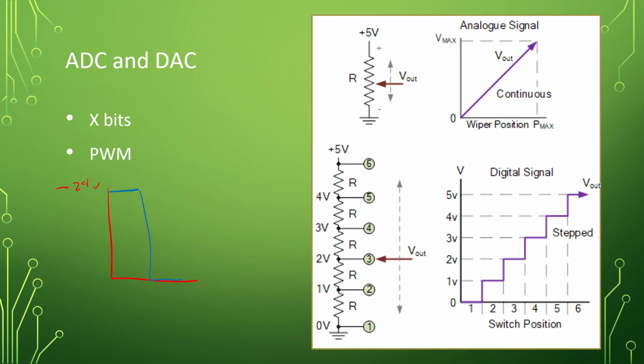Slamming the gas pedal, letting go of the gas pedal. Right? You're never going to get to full speed in your car. You're probably only going to get to half speed because you're only on the gas pedal half the time. So if you average, because that's how most things would see this, they're saying full power, no power, full power, no power, you would now see 12 volts.